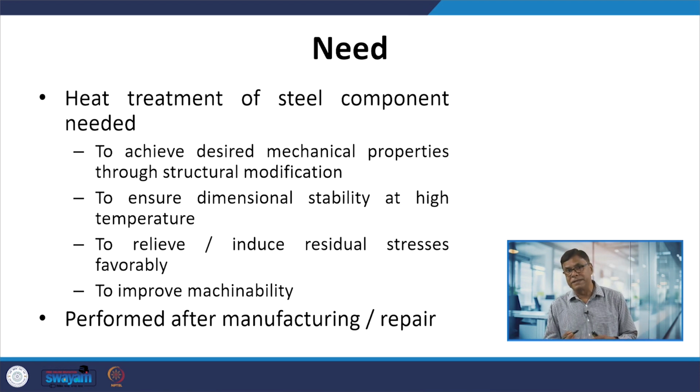of high carbon steel is also achieved, especially in the case of hyper-eutectoid steels, where we have a thick layer of cementite. The thick layer of cementite adversely affects the machinability. So, to improve the machinability of hyper-eutectoid steels, the spheroidizing heat treatment helps in improving the machining.